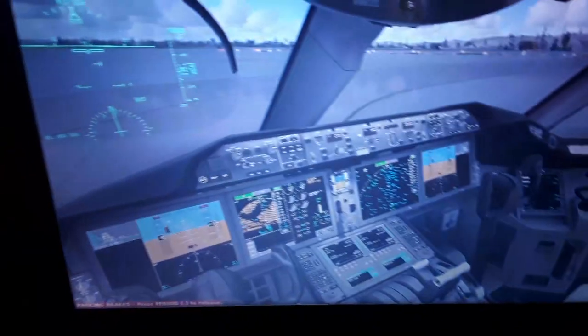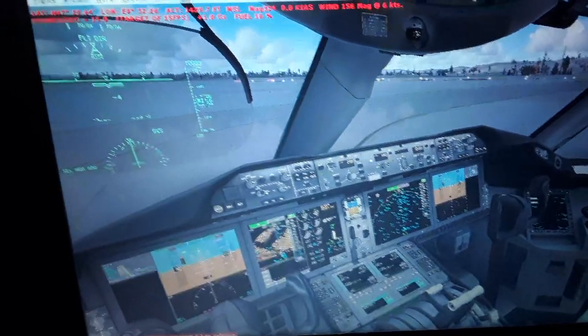You can see the runways we're going to use for takeoff and for landing, the heading of the runway, also the taxiways we're going to use. So you can see also the navigation aids. The navaids displayed are VORs, ADFs and DMEs. Also we have the waypoints, which are horizontal and vertical navigation fixes with altitude and airspeed constraints. The aircraft is going to have to fly through some waypoints as you select the flight plan, and they're going to be connected with the purple line.